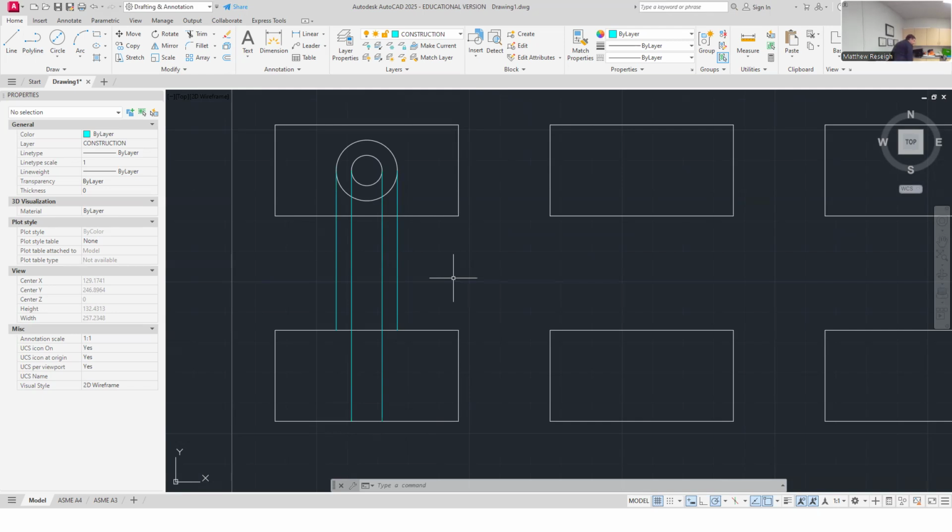The reason why we use a counterbore, the reason why I'm actually wanting to draw these in class is just to discuss, and I'll pass this around, and I'll pass around the one that this is what would need a counterbore. So this fastener is going to go into a plate and maybe hook two things together. We don't know what's going on. I'll pass this around. Counterbore is for that. They call that a hex head, or they call that a socket head machine screw.